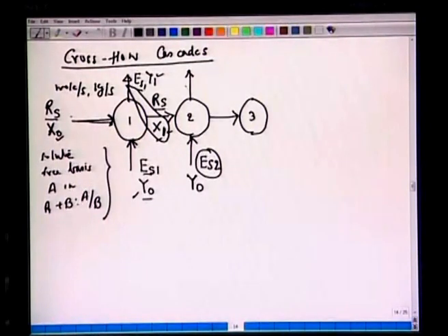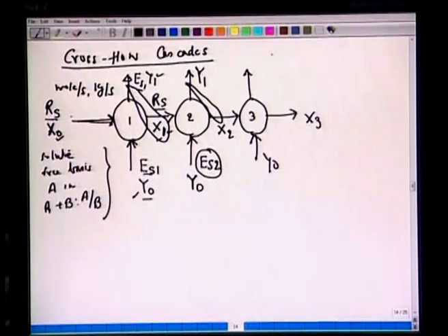Again we can assume that if you have given enough time, the leaving streams with the mole fractions y1 and x2 would be in equilibrium. All right. So, similarly we have x3, we have y0 and we have y3 here. Excuse me, this should be y2. Okay. So, we are following the nomenclature that the leaving streams have a suffix, for example 3, which originates from stage 3.